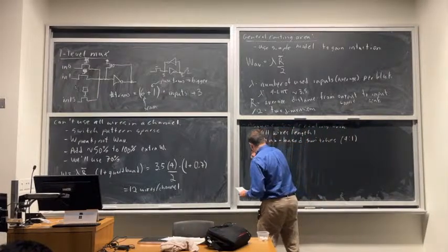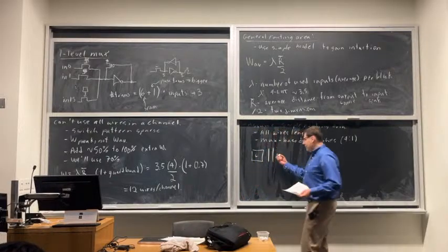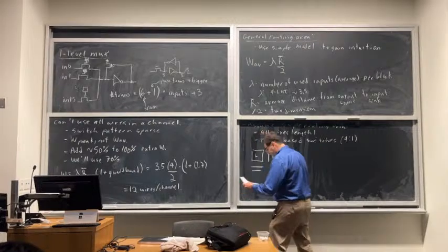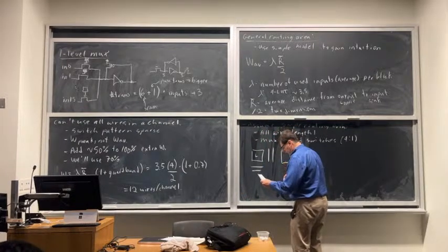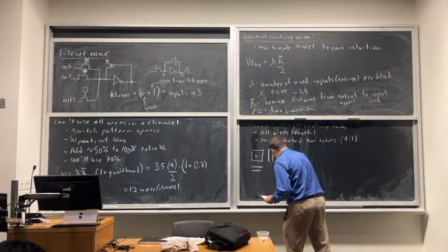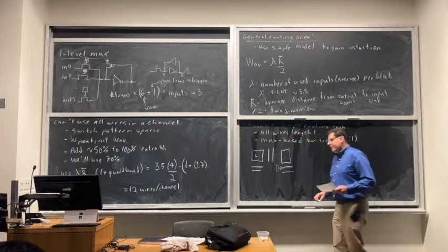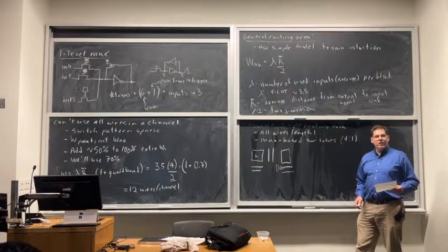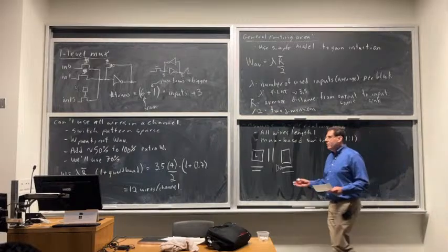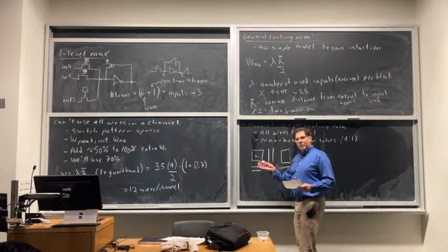Okay, so what does this look like? We've got a lookup table. This will be a channel width of 2, so we're really doing 12. And every single one of these wires is going to have a mux in front of it. The mux is going to be built as a 1-level mux because it's very small. For a mux this small, a 1-level mux actually works very well. We don't need to go to 2-level muxes.